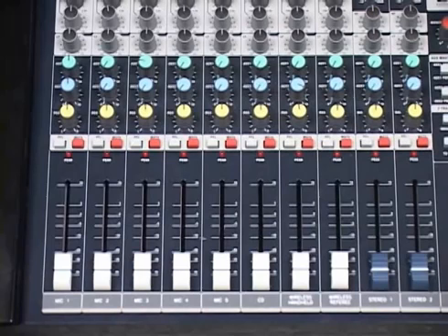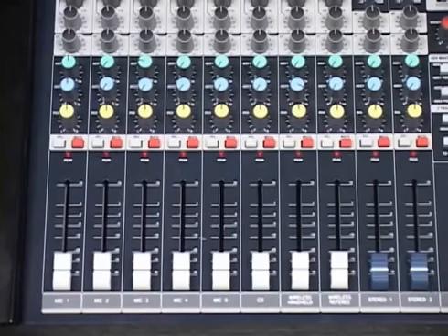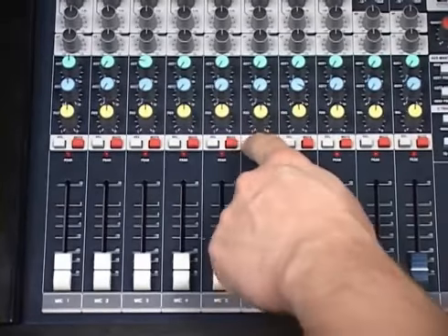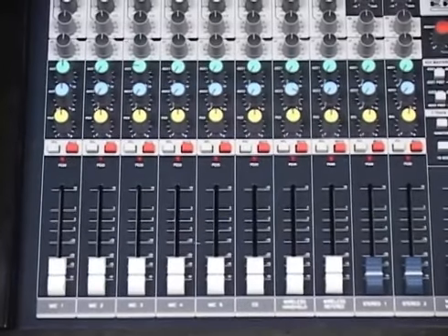The final step in setting up your system will be adjusting the gain structure. Do this to each individual channel that is actively being used. The process is the same for each channel, so we will only cover this once, and then you will repeat it for the rest of the channels. Make sure that the master fader is all the way down. Next, select the PFL button on the channel you are adjusting to get the signal level to appear on the